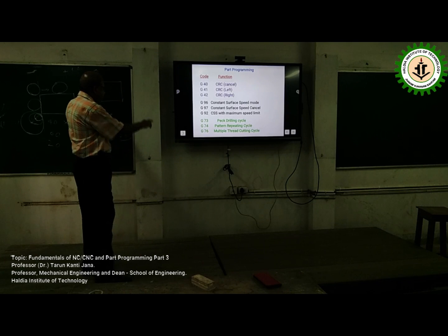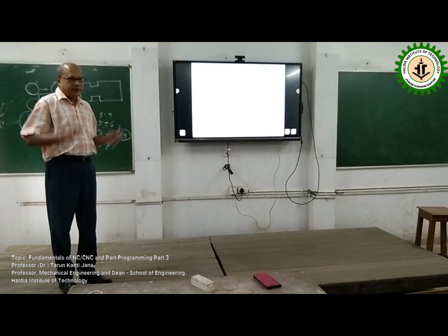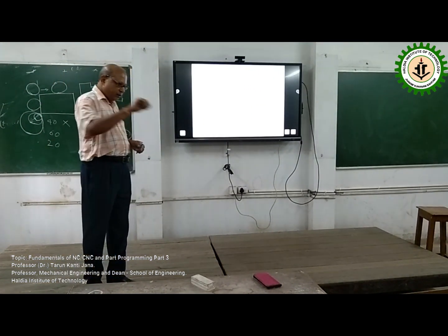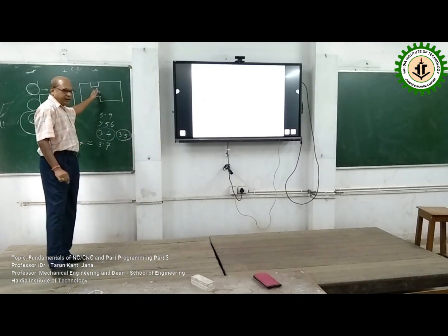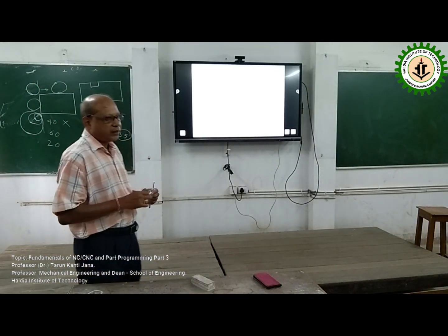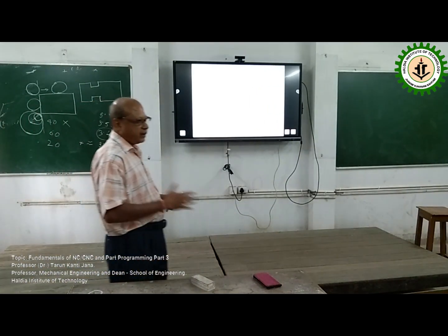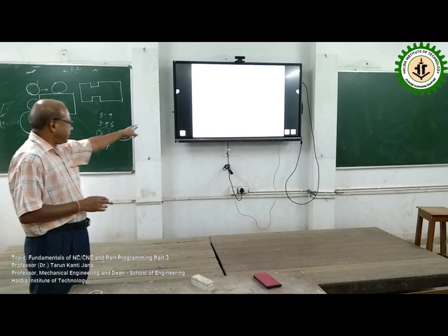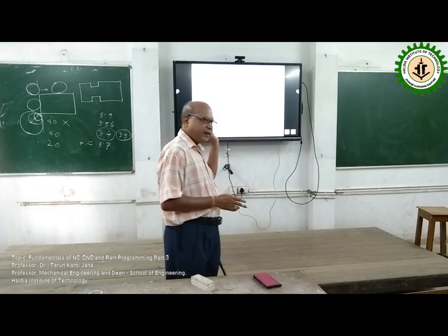Although I forgot to mention, there is G74 or 75, which is called the pecked grooving cycle. Pecking means some penetration, some withdrawal. It does not move the entire distance continuously, to give more life to the cutting tool. Otherwise, there will be very high heat generation and continuous force exertion. To give certain relief and for better evacuation of the chips, a pecked movement is given, which is possible or developed in the case of drilling as well as for grooving.